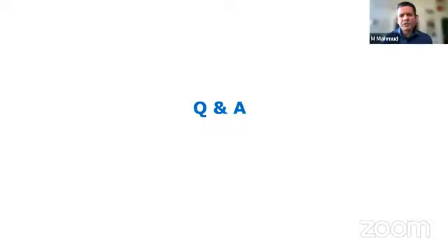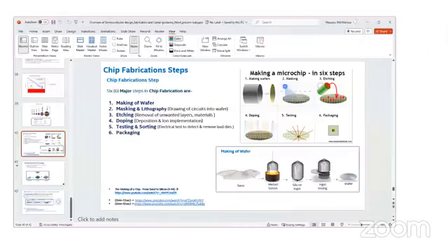Yeah, if I may add, Manju, real quick. Sure. It's a round shape because of the way the ingot that Ashfaq referred to, the way the silicon crystal is seeded, and the ingot goes in a circular motion. So the ingot comes out like a big wide rod. So that's why. Right, when you crystallize the sand, when you make the ingot, you liquefy the sand and make a crystallized form, right? It comes out in a cylindrical shape, right? So when you cut from the cylindrical shape, it normally comes out as a circular disc where you can add the circuits, the wafer, right?